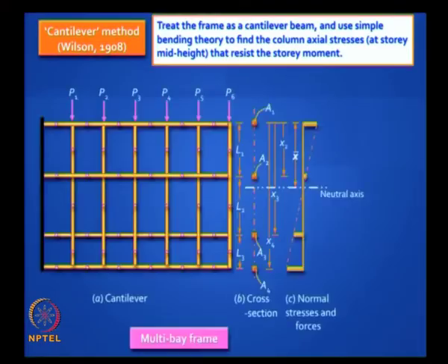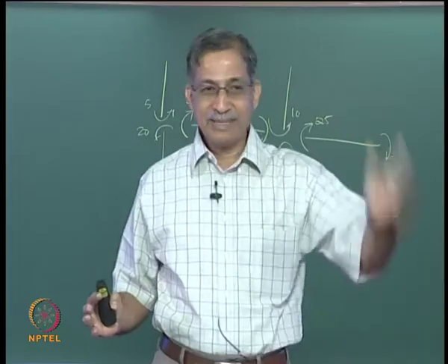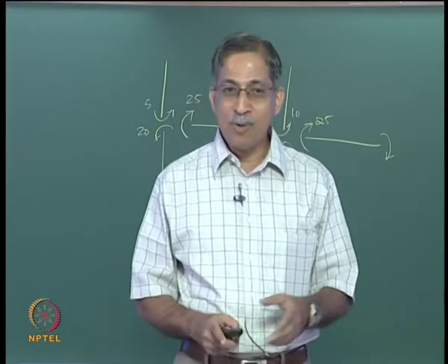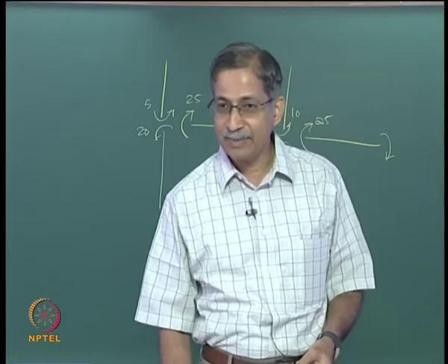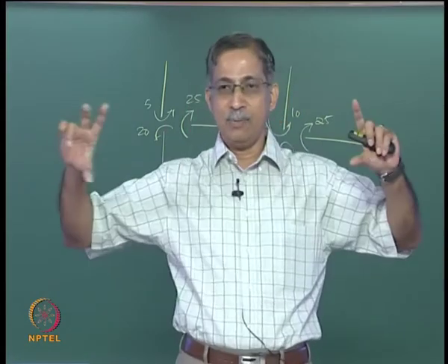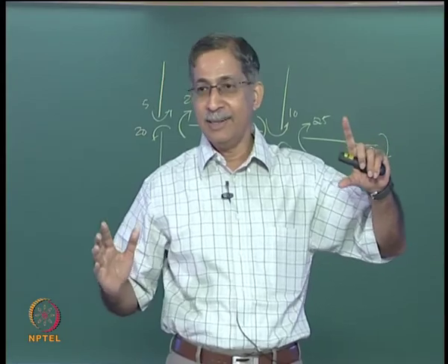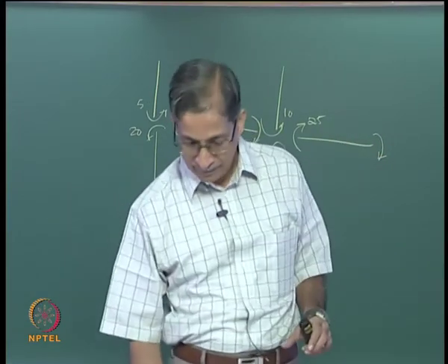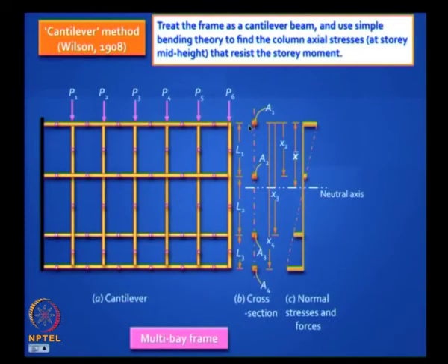So for convenience, let me rotate that frame by 90 degrees because we are more comfortable looking at cantilevers which are horizontal, right. So I have rotated the whole building 90 degrees in my mind and fixed the left end. So it's got an open web section. Do you understand? That means usual beams are one piece with solid cross section. This is an open web section. That means I have the solid areas only located at the column location if I cut a section anywhere, right.